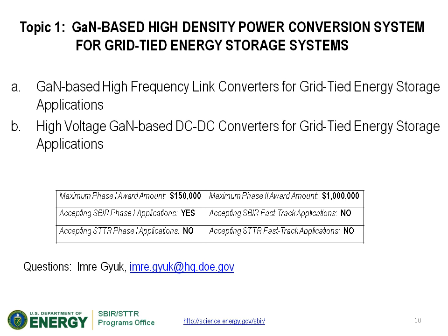As far as the requirements for this topic: greater than 600 volts DC link, greater than 50 kilowatts power, 480 volts AC output, junction temperatures greater than 120 degrees C, and greater than 15 kilohertz transformer. The design must show significant improvement over traditional systems.